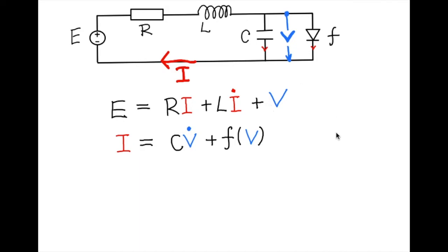So here I will assume that we already know that as time goes on, the system stabilizes, the V will become a constant and the current I will become a constant. So basically we are taking t to infinity in both equations, and because I and V will be just numbers, they are constants, and the derivative of them will just become 0.